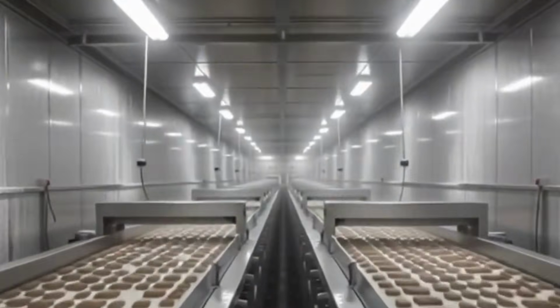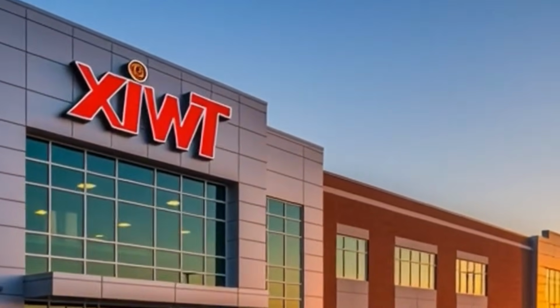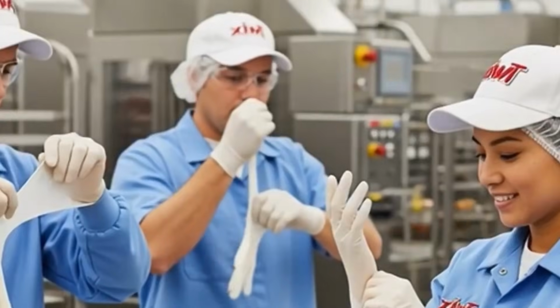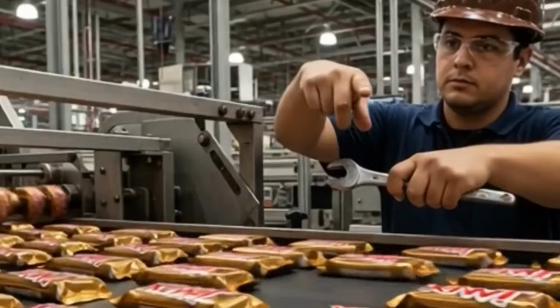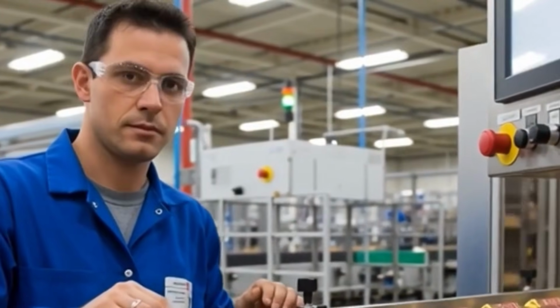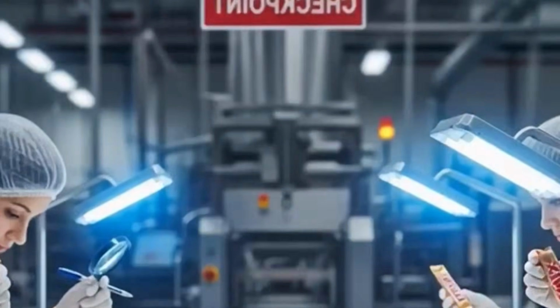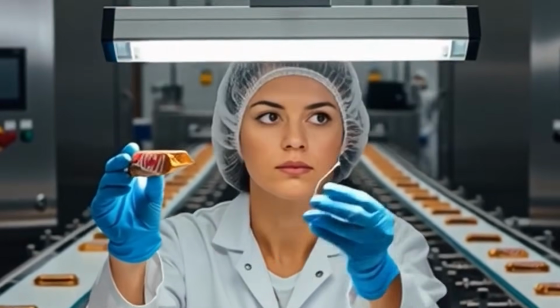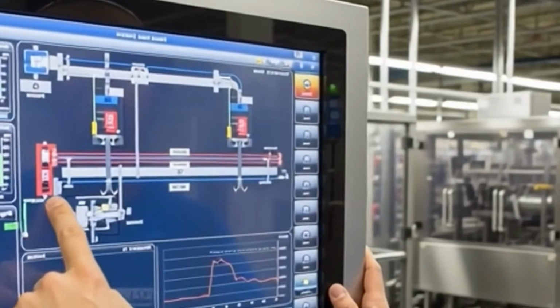The enrobed bars enter a cooling tunnel set to 10 to 14 degrees. The tunnel is 20 to 30 meters long and provides 3 to 6 minutes of cooling time. The goal is to solidify the chocolate coating to a firm, glossy finish without causing thermal shock or shell fractures. Airflow patterns and tunnel humidity are tightly regulated to prevent surface bloom and condensation.